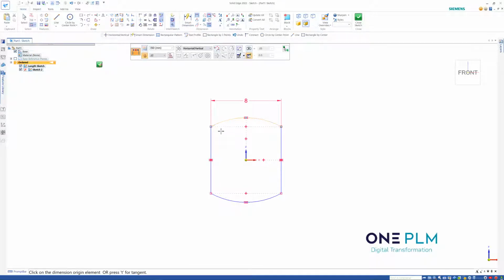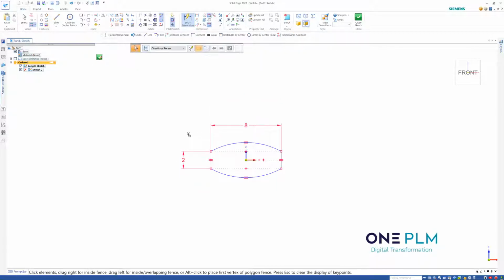And then the size that I want on here, that can be 2 for now, but really I want that to be linked to the size, so that's going to be size divided by 8. So if we double click on that, that can be size divided by 8.